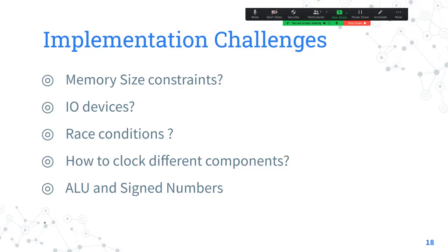If you want continuous read, which means that as soon as I change the address, the read value should change, even if it takes some time, then I don't have to clock it, and I don't have to give a separate cycle to read that. You can assume that when you give this address, by the next clock the output will be there. There is no intermediate clocking. If you want clocked reads, you can use block RAM, which is a separate part of the chip. So if you want continuous read, then you will be using LUTs.